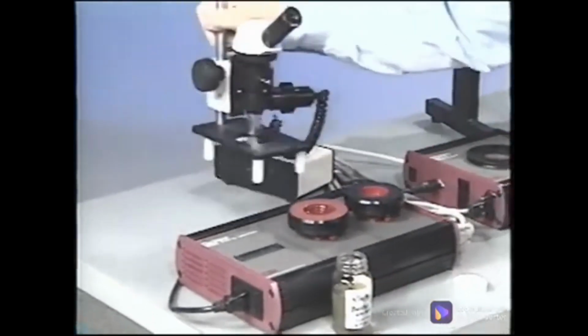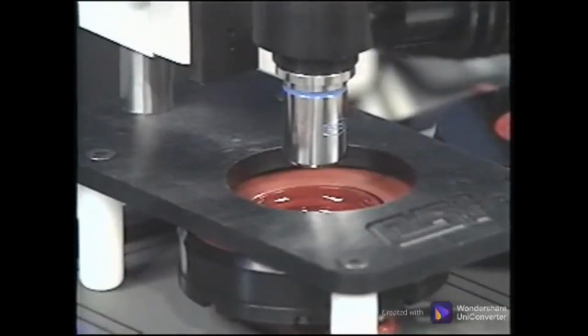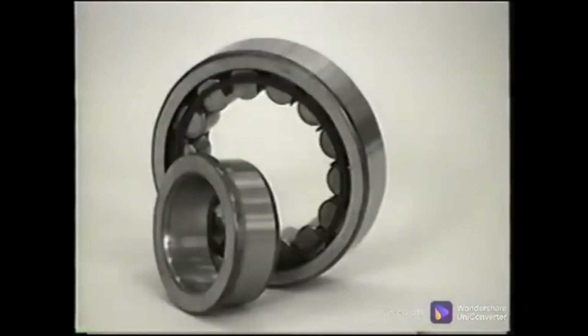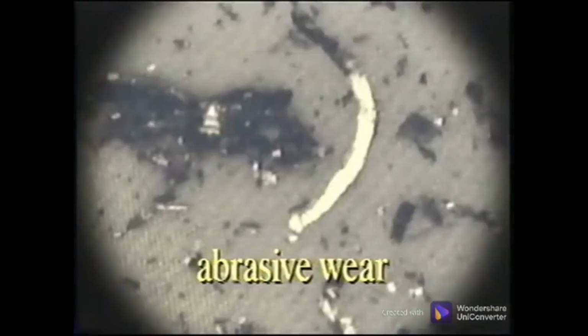One group of wear particles is caused by a 3-body system. A system typically has a 2-body system, that is, 2 components of a bearing, for instance, are separated by a thin oil film. When a 3rd body, such as dirt or silica, is in the film, it will cause scraping or gouging of the bearing components, creating a long, narrow particle similar to a machining swarf. When this abrasive wear is present, find the source of the abrasion and remove it.